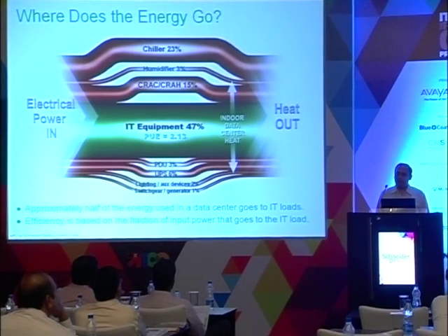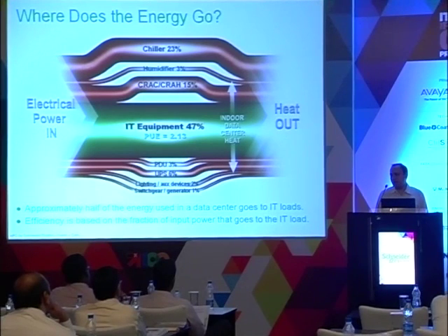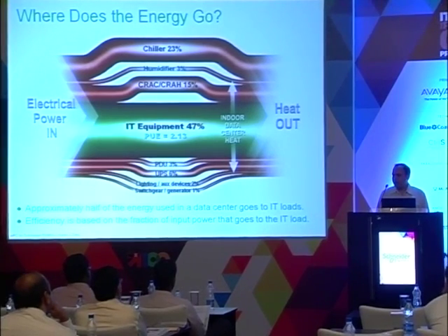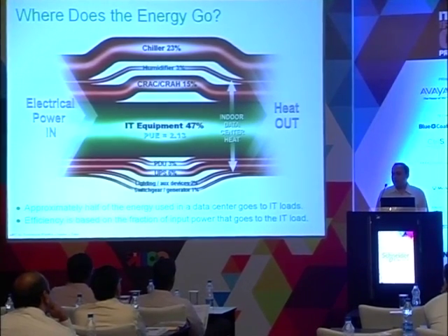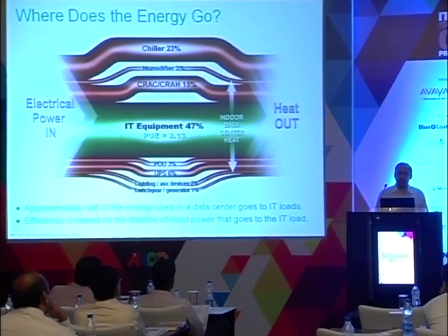So if we have a tropical climate like the one that we have in India, where it does get pretty hot out there, we'll have to put more energy into our compressors to pump that heat out. So obviously, if I have an equal running efficient data center, one in India and one in Colorado, just because the Colorado will show an efficiency of PUE of 2 and we will be showing a PUE of 2.2, we may actually be better off than the Colorado data center, right? So we need to be very careful how we use that PUE as a metric.